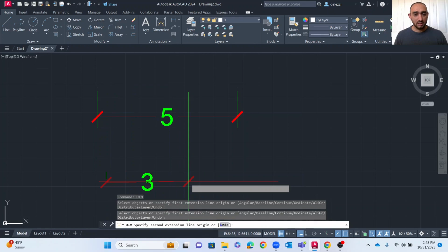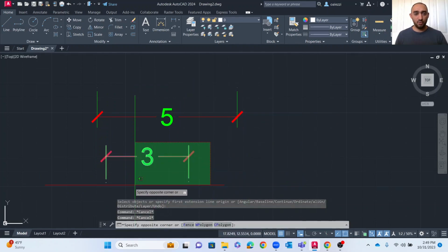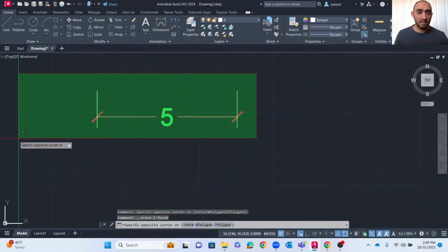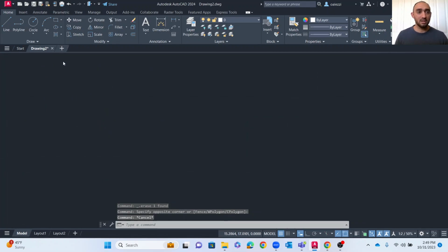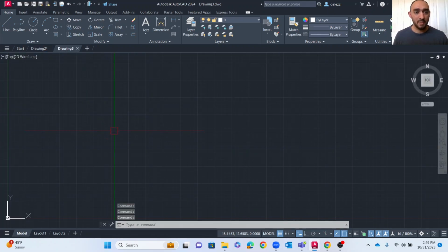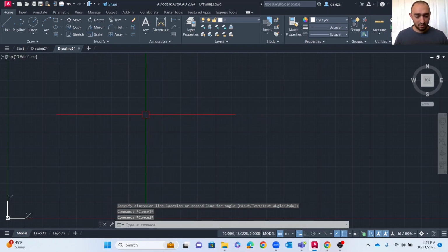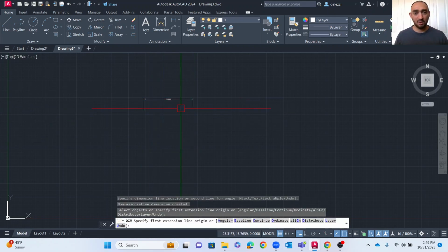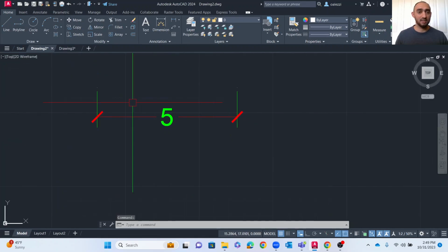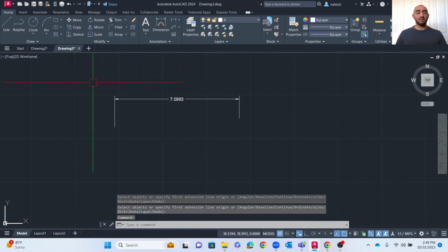Then now we create this dimension style. So for example, see, we create this dimension style. If we would like to save this dimension, so if you notice next drawing, when I open a new drawing here and I would like to use the dimension, it will not save. It will give me the dimension, the standard one. See, it's different than what I create. So in this case, instead I will go and create a new dimension style from the beginning.